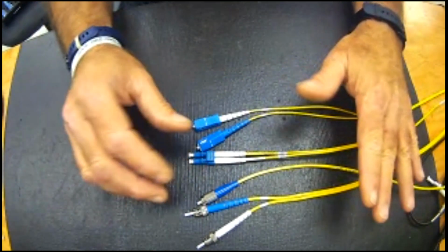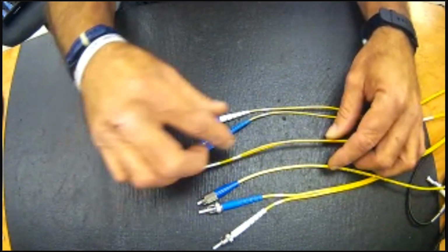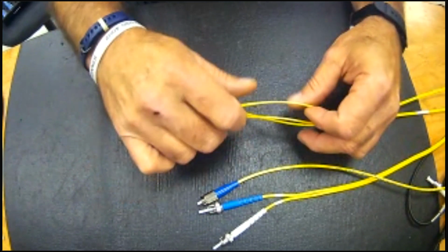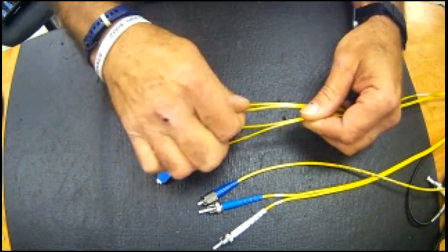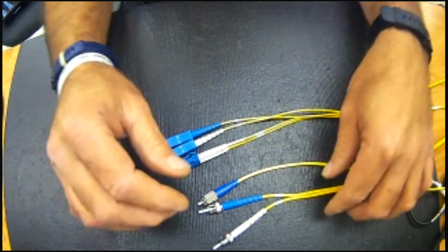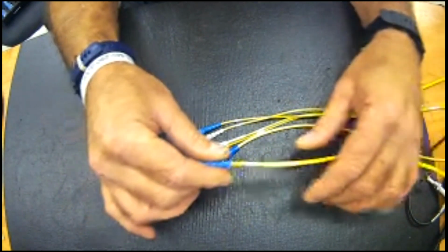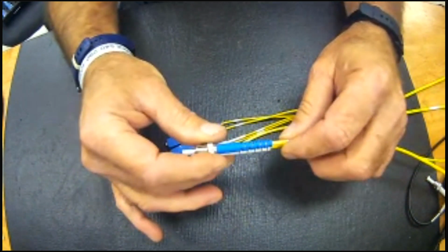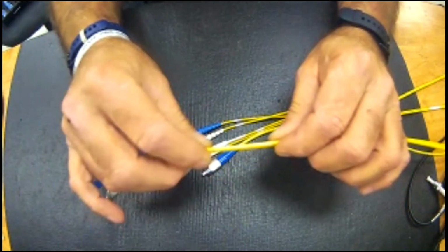The other thing with patch cords is diameter of glass. If you're in a 96 position patch bay, you're going to have 96 duplex cables side by side. 1.8 to 2 millimeter in diameter is probably what you want to go with. But if you're going to make a patch cord that's going to go from a media cart to a wall for a disconnect, and people are going to actually plug it and unplug it routinely, you're better off with a 3 millimeter in diameter.